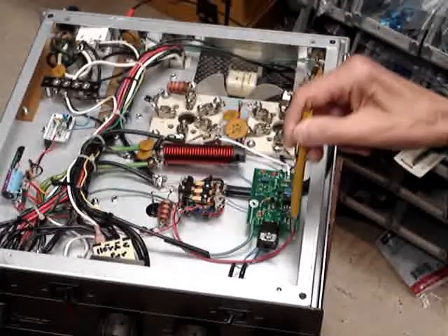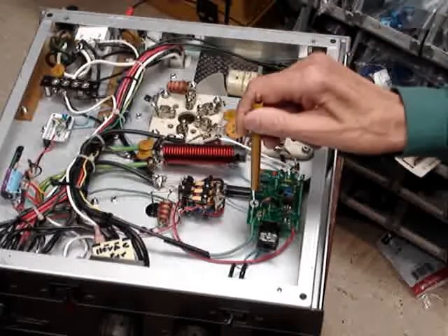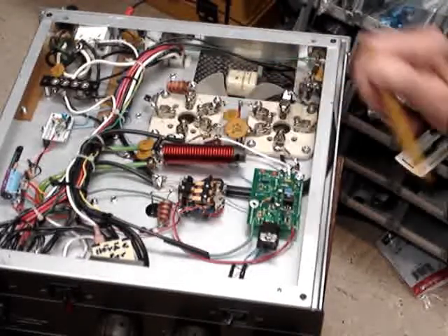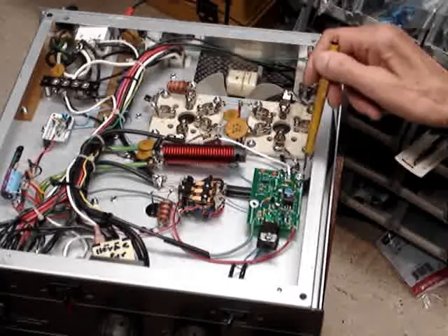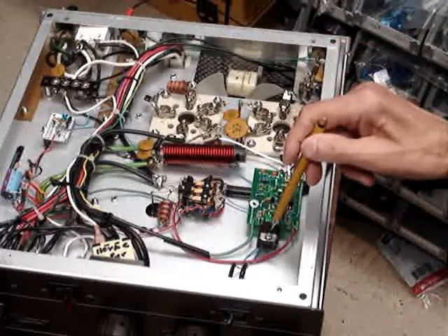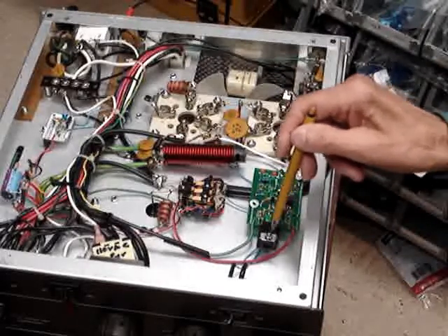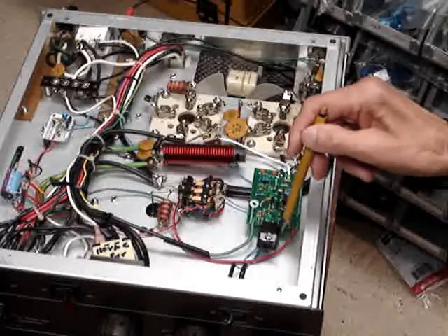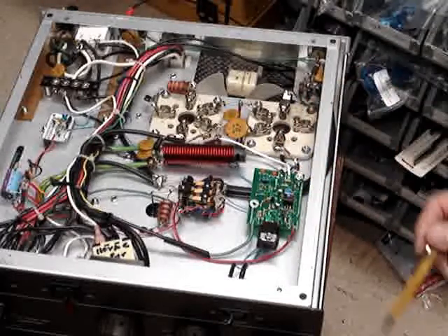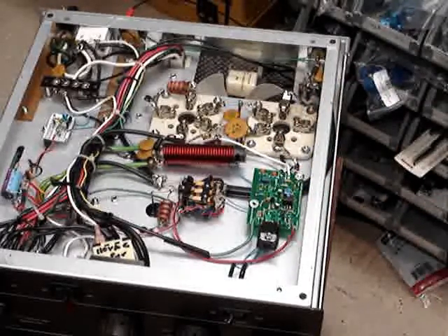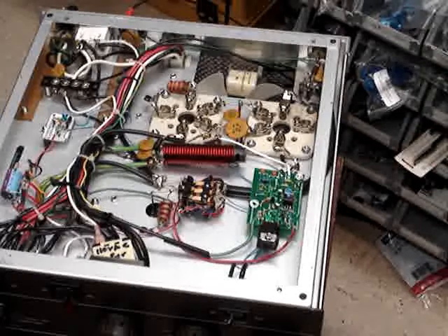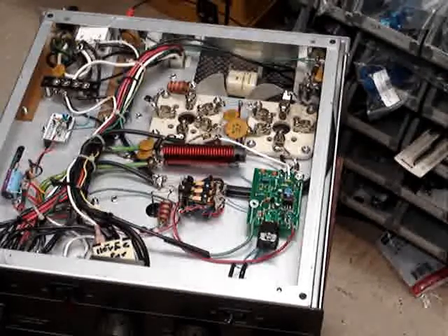This is very light, and there is another hole available here if you wanted to put another standoff. This is at ground potential, and these are ground potentials. However, this is at the bias potential, so you don't want this to touch ground or anything else unless you insulate the transistor, which it's not now. And that's it. That's electronic bias system as applied to an SB or HL2200. We'll show you a little bit how it works here in the next part of the video.